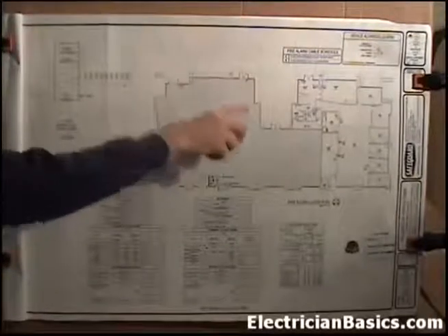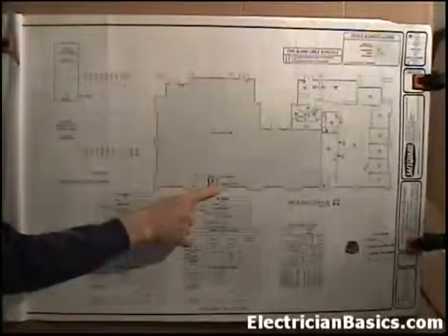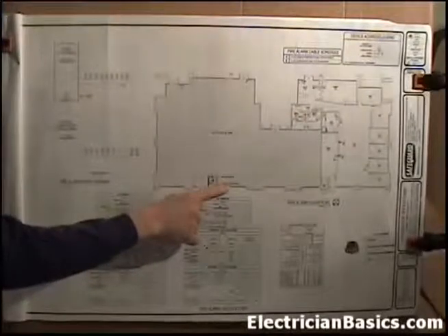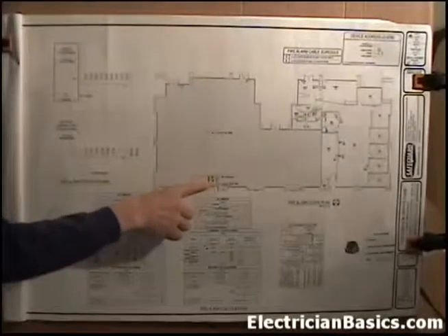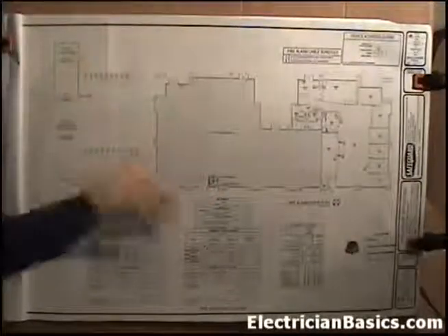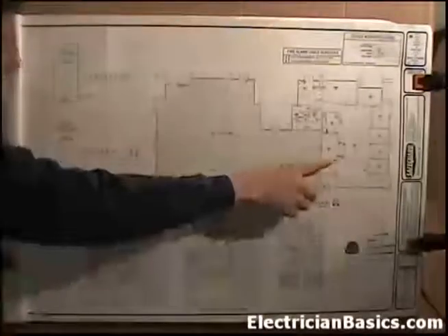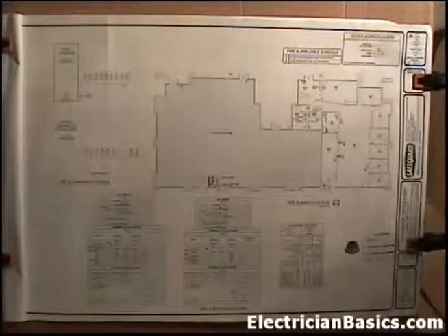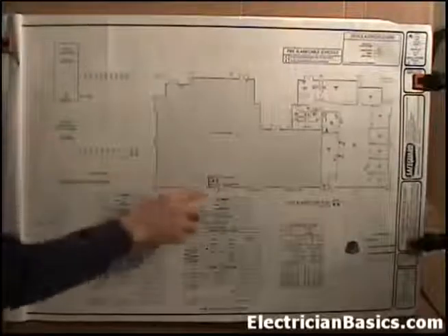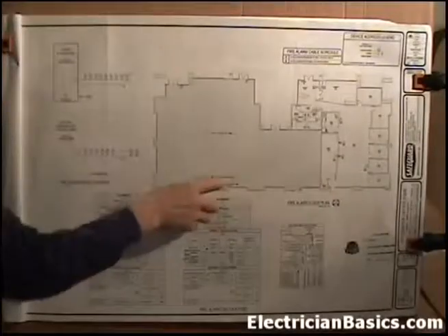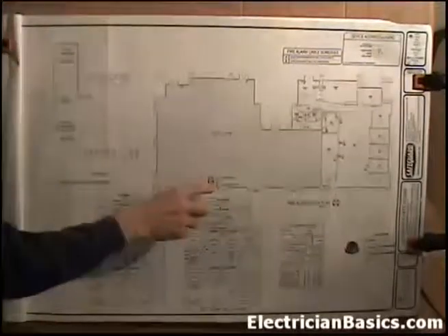Now let's look here. Here's the entire building, and here's the riser room. Now it says here, new power supply and existing control panel, Gainwell 602, which is this here, which we're going to talk about later. So this NACPS, new power supply, our fire alarm control panel is going to be located in a riser room, which means you have to get a conduit to go from here over to our build-out area. It also means we have to have a conduit coming back for the return loop, because they must be in separate conduits. In other words, you can't go out to a junction box, run it through, and then come back from the junction box. It has to go out, run your loop, and then come back in a different conduit.